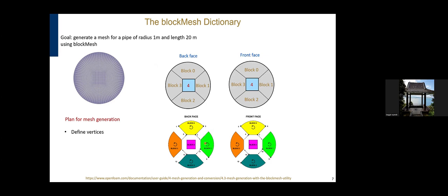And so for block 1, we only need to define 2 front vertices. We define for block 0 the front, and then we define for block 0 the back. And then we have to do the same thing for block 1 and all the other blocks as well, right? So for block 1, the back is exactly this: 4, 5, 6, and 7, anti-clockwise. And then we go to block 1, which will be 8, 9, 10, 11. And the same thing, we'll just have to continue.